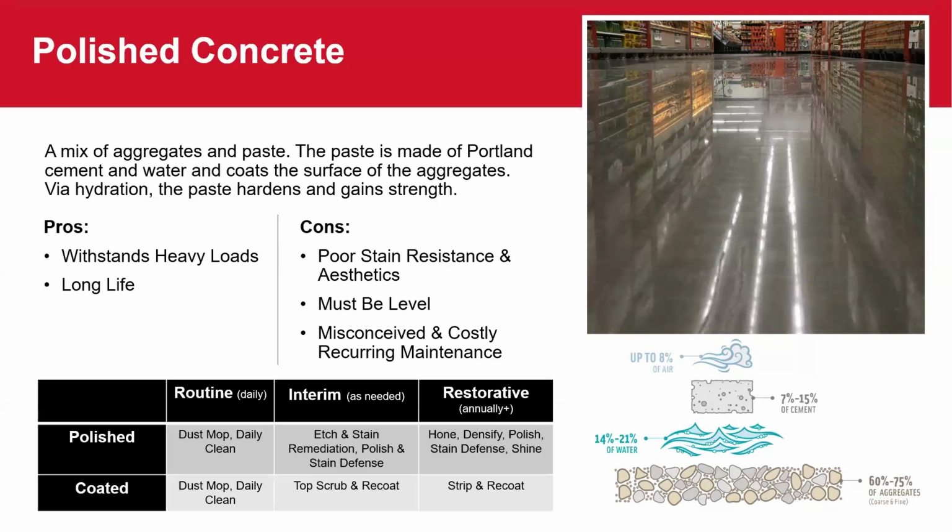So on a polished concrete floor, in the life cycle of floor care, routine, we're going to dust mop and daily clean with a wet mop or an auto scrubber, preferably an auto scrubber. Interim, we're going to remediate etch and stains and polish and stain defense. There are a lot of companies out there on their maintenance program or polishing program that are not using densifiers or stain guards. We're a firm believer that densifiers are very, very important to polished concrete floors to harden and prepare that concrete for the polishing and for the traffic that's going to go on that floor.